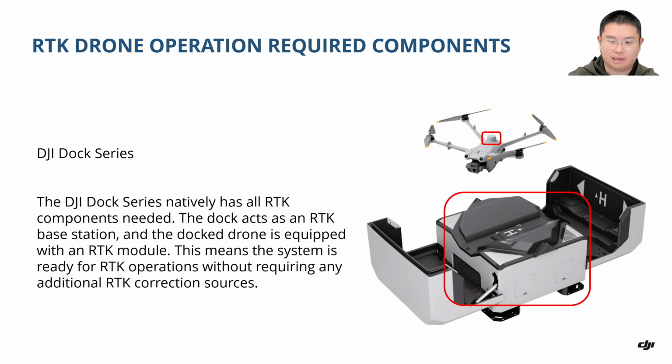The biggest con, which also happens to be the biggest pro of network RTK, is the internet connectivity type. You will have to connect to a public network or internet to obtain RTK service. However, some operation areas may not have reception at all. In that scenario, you just cannot use network RTK.